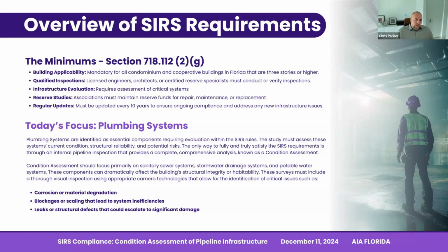So we typically see the corrosion, the material degradation, especially in buildings that are built in the 50s and 60s. It's almost primarily all cast iron pipe. You put cast iron pipe in a coastal environment between salt water, sand, it's going to already accelerate that corrosion. And it's not atypical for us to go to a building or go to a facility, perform these inspections, and have almost no pipe left, or the cast iron is in such a brittle state, it's almost like a material